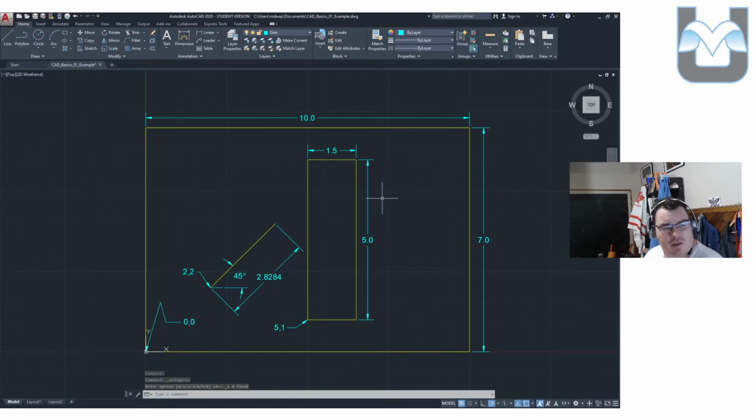Two more things. Let's draw a circle, and let's draw one more line, and it's a tricky line. Okay, we're going to do the circle, and we know that our circle starts in this drawing at 8.5, comma, 5.5. There you go. Okay, and it has a radius of 0.75. Now, if I wanted to draw a diameter, you'll notice that at the bottom of my command line, I actually have the option to just type in or press diameter. I'm going to draw that in, and I'm going to realize that, hey, I put this in the wrong layer.